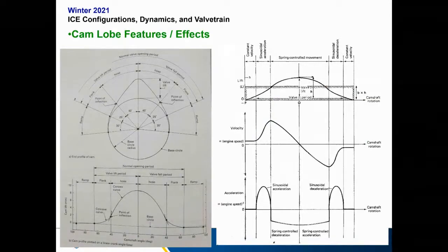Okay, so as we have this camshaft, it's basically a shaft where we have these rotating lobes, or different lobe profiles, which allow some type of connected mechanical device to move up and down so we can actuate the valve. So if we look at this lobe profile here, we can see that as this camshaft spins, we have different profiles for the valve lift, for the velocity of the actual valve, and then the acceleration of the valve.